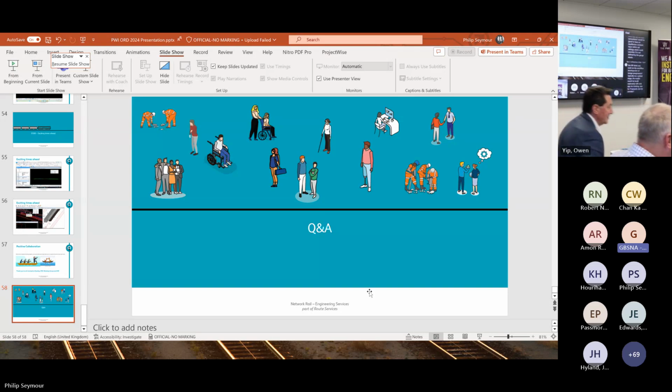Right, we'll go online again. Another one from Alexander. Can the chainage in the vertical profile be fixed to whole chainages instead of being set to the changes in the horizontal geometry? The whole chainages. Oh, instead of, yeah, we didn't do anything there. But yeah, you can set the chainage anywhere. Yeah, you can have station equations if you want. So add on, station plus 50 or something. Again, the vertical will link to the horizontal.